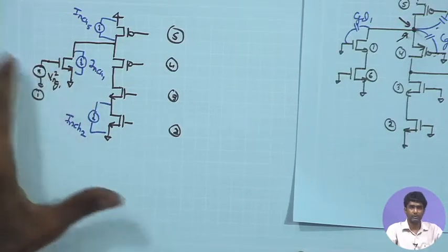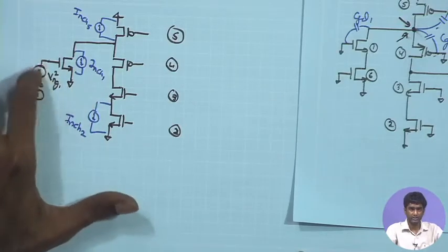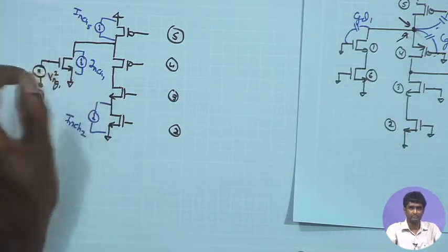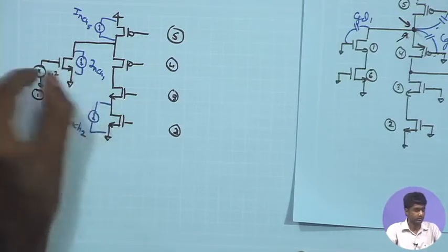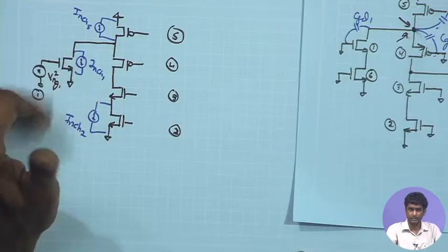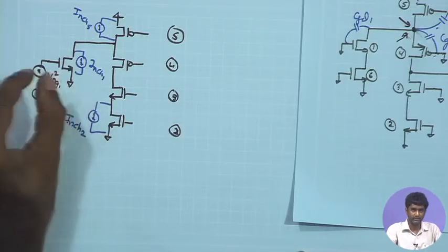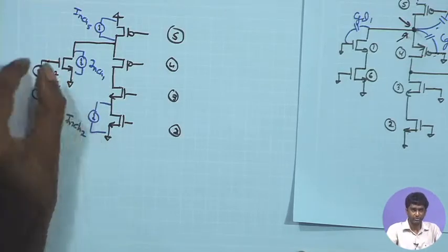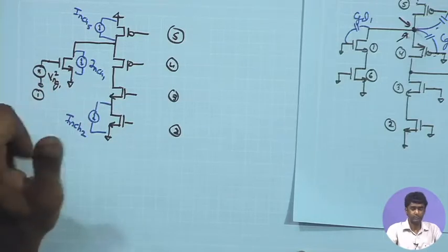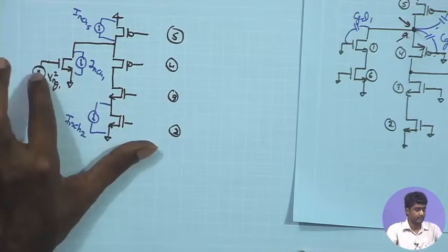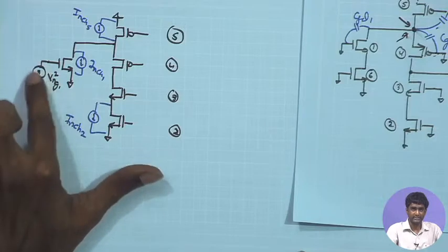Of course, for the flicker noise we anyway represent it with a voltage connected in series with the gate, because the mechanism of flicker noise arises from the interaction between the carriers and the dielectric, and effectively results in a VT shift for the MOSFET, and that can be modeled as a gate voltage in series with the MOSFET.